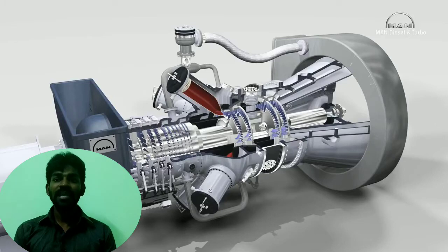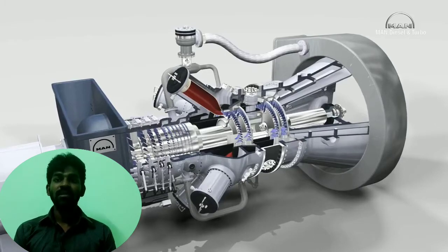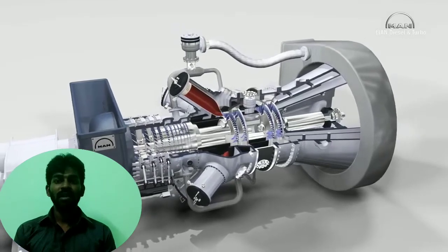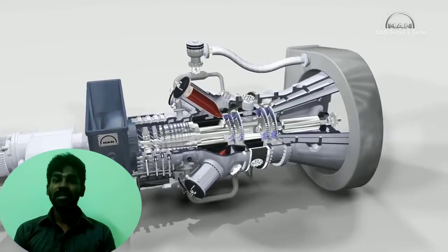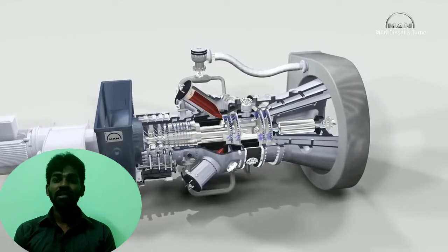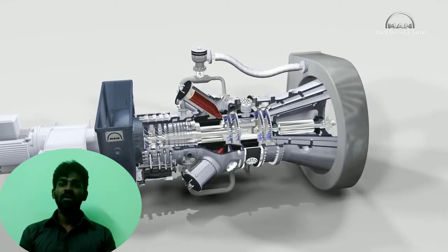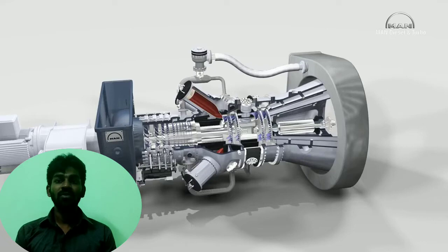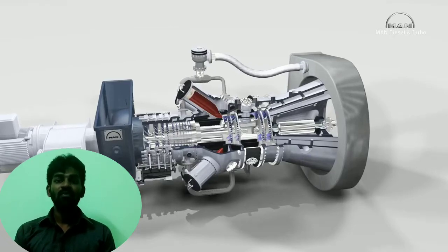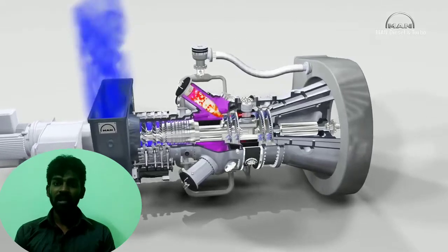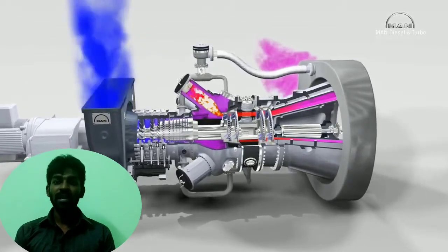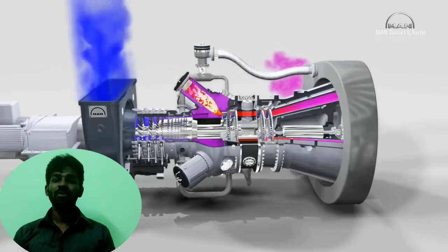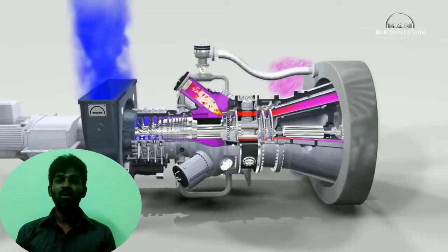The next air standard cycle is the diesel cycle. Here the diesel cycle consists of one constant pressure process, two adiabatic processes and one constant volume process. In this case we need to find the efficiency of the diesel cycle with respect to the work done to the heat supplied. The work done is the combination of all four processes: one constant pressure, two adiabatic and one constant volume.